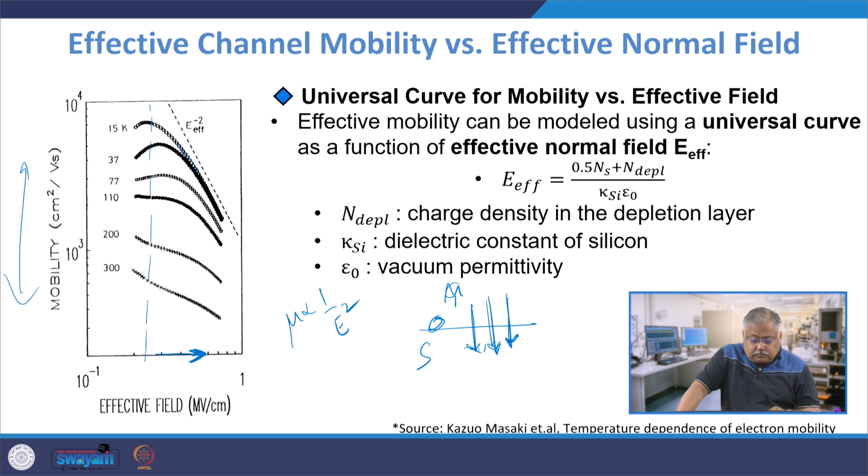However, again please keep in mind that the drop at 15 Kelvin is very high as compared to the drop at 300 Kelvin, and this is where the variability study for cryogenics comes into the picture. You have to be very cautious that at low temperature the sensitivity is very large and therefore you need to model that as well in order to have a stable electronic system.